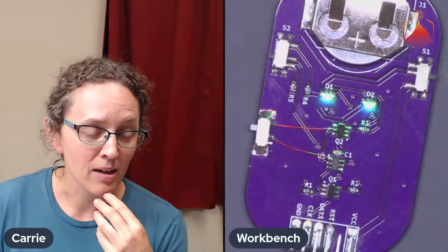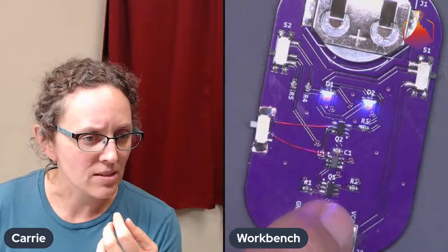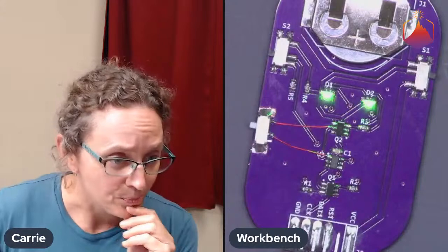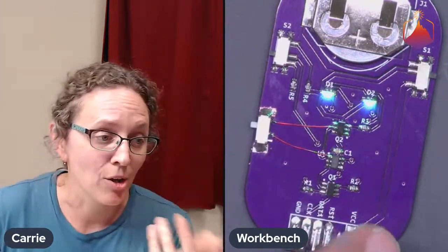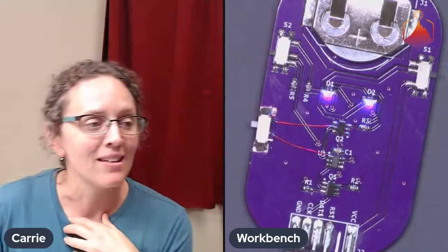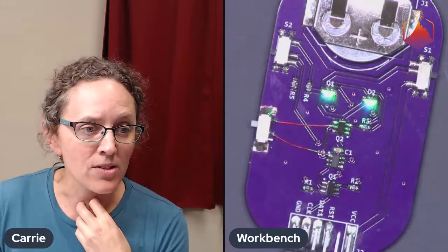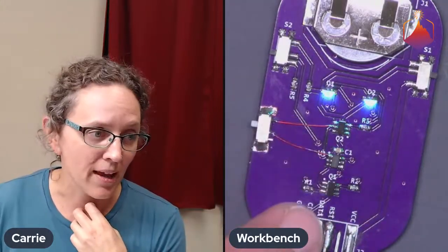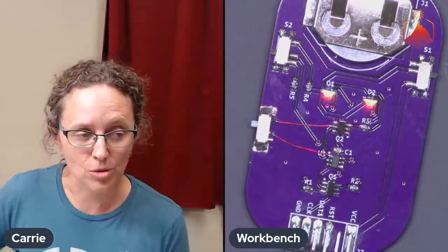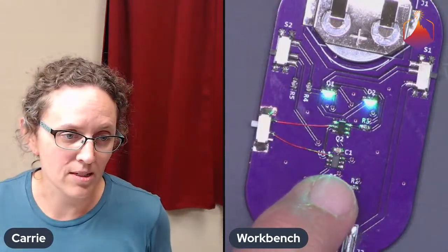And I am doing this with an ATtiny4 processor. Where are we? Right, we're in the middle there, right there. And I know they're all SOT-23-6 packages. That's just what the name of this size of component is called. And there are transistors that are essentially turning the power on and off to each LED color. And the processor is the tiny chip in the middle right there.